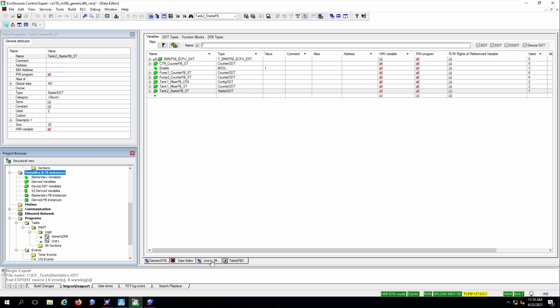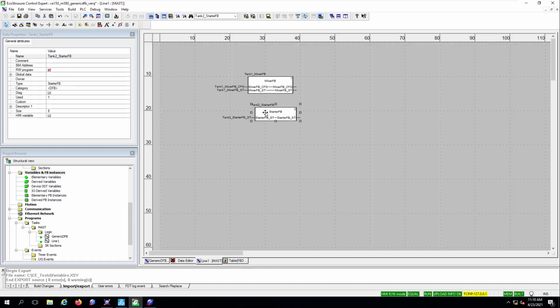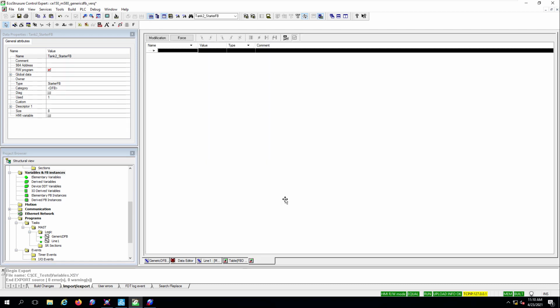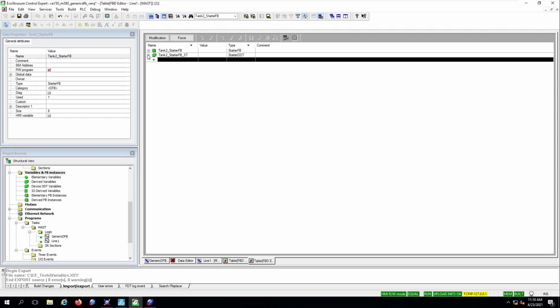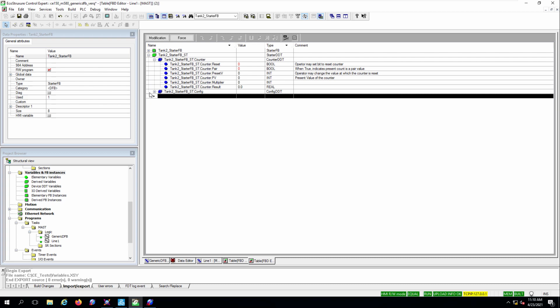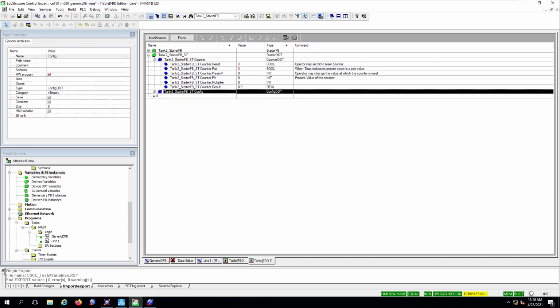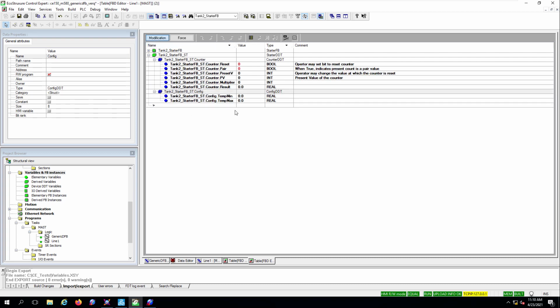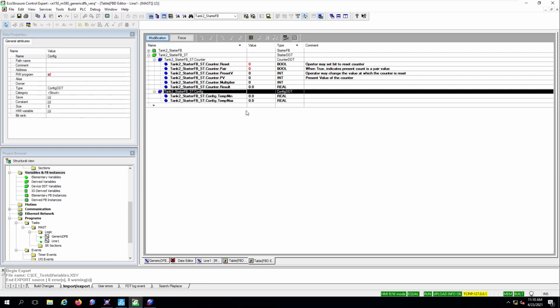Let's put in some values in an animation table, and I will take this opportunity to point out that in the placeholder address in the AVEVA System Platform derived template that we need to create for tank2, we will need this complete path for each attribute.